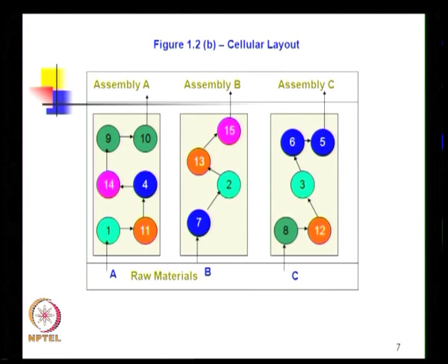So, as variety increases, can we have different types of design of cellular manufacturing, where we could have something like a service cell and dedicated cells? So, the parts can move to the dedicated cell, and let us say we create one more service cell which contains one orange machine, one blue machine and one green machine, and say that if you need some additional requirement, go to the service cell, get things done, come back to your original cell, but do not go from one original cell to another original cell.